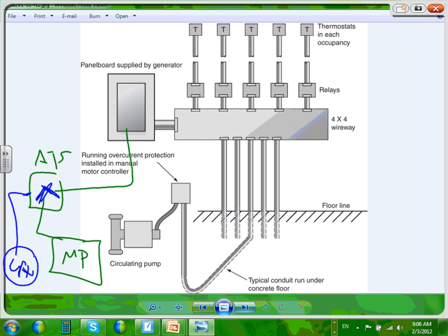You lose power, there's a battery in the auto transfer switch that sends the signal to Mr. Generator to come to speed, energize, start. The engine of the generator auto starts. If it's an emergency generator, the whole start and synchronize and come up to speed happens within 10 seconds. Now it will switch you into the generator, so all your heating cooling system will be backed up. If you lose power, basically you don't lose heat.